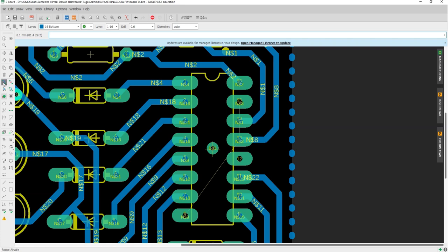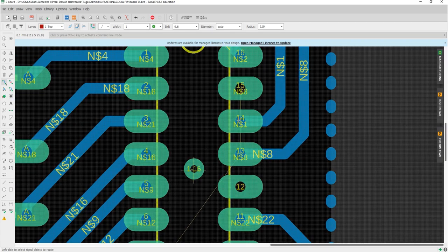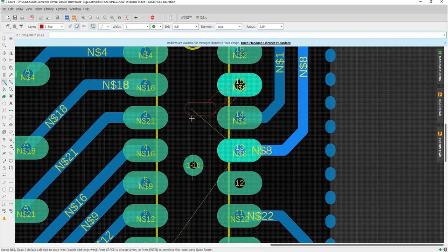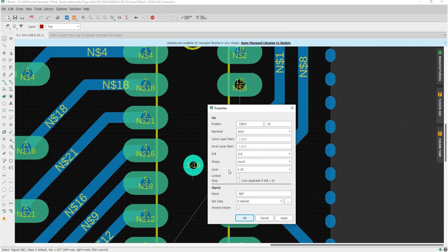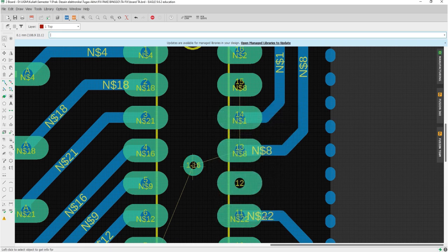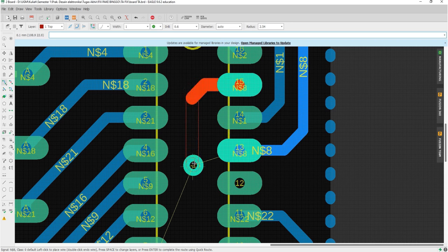This comes in handy if you ever need to channel heat away from one of your super-powered components, like an integrated circuit or IC. By placing multiple vias below the die of an IC, you'll be able to lower the operating temperature of the component, which will, in return, make your design all that more reliable in the long run.